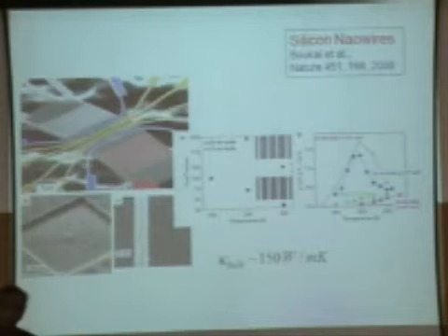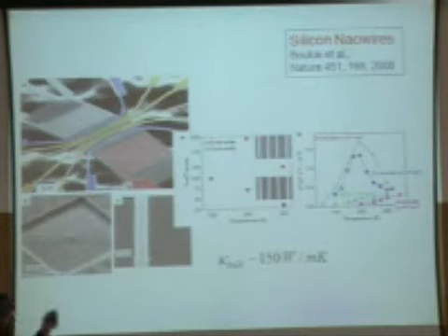If you can reduce that phonon conductivity by a factor of 100, of course, this is too big. So therefore, bulk silicon is not good. This ZT is 0.01. But by reducing the conductivity, 150, by a factor of 100, you have a tremendous increase in possibility. So that's point number one.